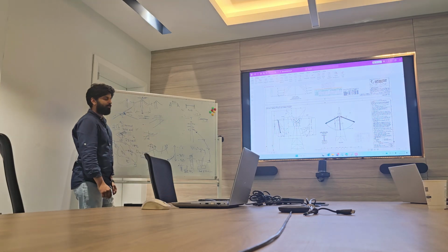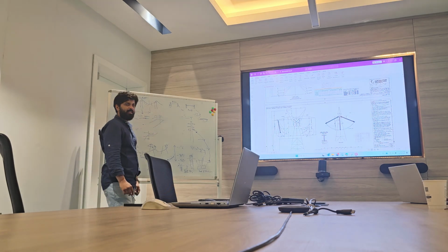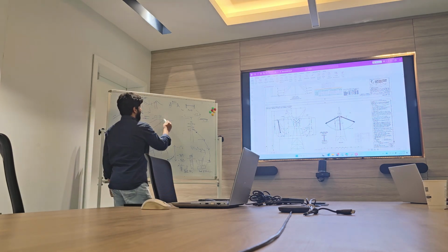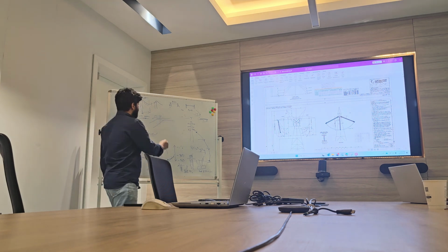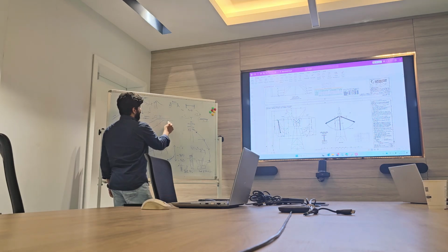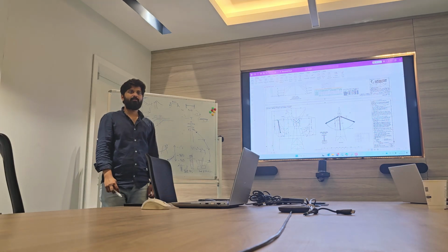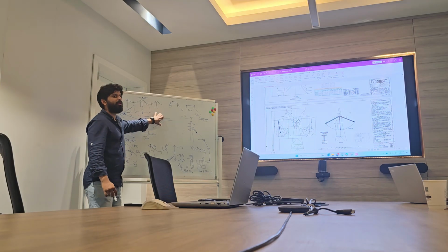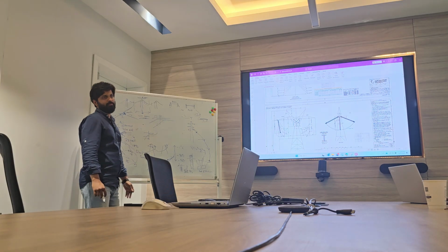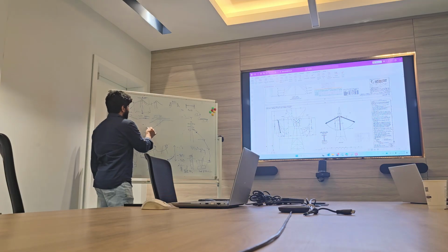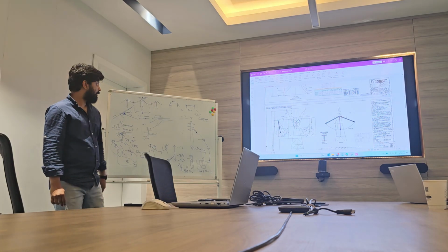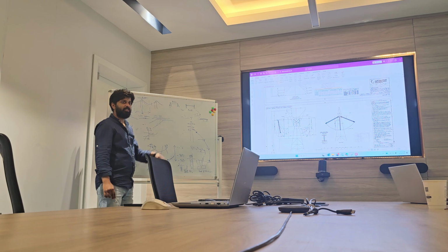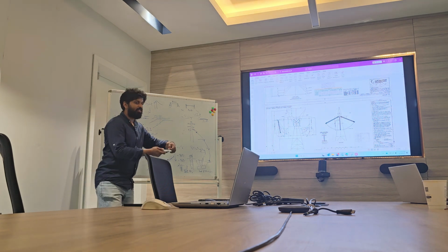This is hanging, this is suspension. A tension tower is like this, and you have incoming and outgoing. It means there is some tension from here and some tension from here. At every angle point you have to put a tension tower. A suspension tower will not work. It will work only up to a maximum, sometimes designed as 0 to 4, sometimes 0 to 2, meaning only for a straight line. If you have more than this, you need to put a tension tower so that you can change the route of the line.